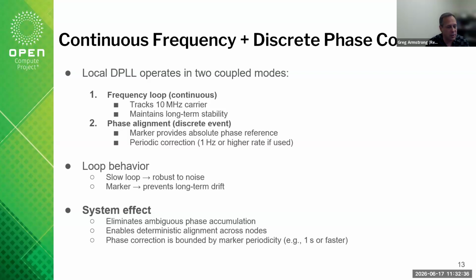You don't need a big, huge OCXO to stabilize the clock until you figure out what happened to that 1 PPS, to say, well, I better just sit here and hope I can stabilize long enough until I figure it out or find another source. The 10 megahertz is allowing you to maintain that. You could almost wait forever, as long as that 10 megahertz is traceable to the same time card constant, or maybe it's traceable to a very good OCXO, but it's only one card that has that component. Not each card has to have its own OCXO or a very good TCXO to maintain that constant stability. And like I said, everything else becomes a known behavior, right?